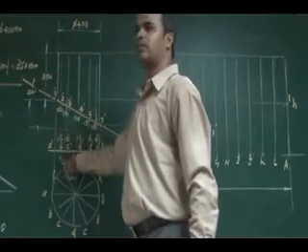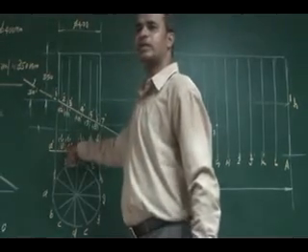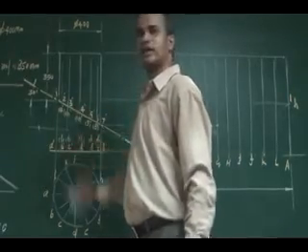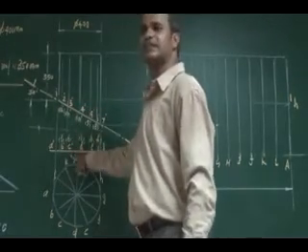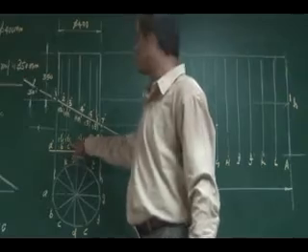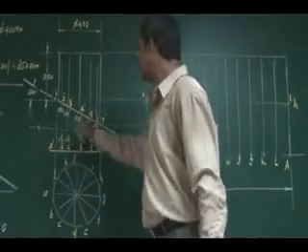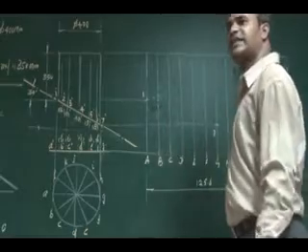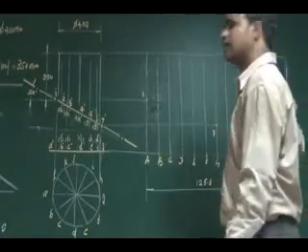Cutting point 2 is on generator B, 12 is on generator L. Similarly 3 is on generator C, 11 is on K. So 4 is on D. Correspondingly you can project it similarly on the corresponding generators in your development. You can mark those points.